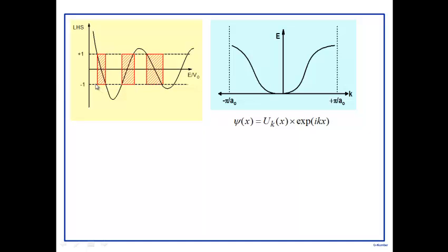All the electrons in this band, which is completely full, cannot contribute to current. Everybody can see? Qualitatively, here is a band. Note that the difference between the two bands' energies is large. In a real crystal, each bandwidth may be 0.5 eV, 1 eV, or 2 eV, something like this. And the forbidden gap between two bands is also of the same order, 1 eV or so.